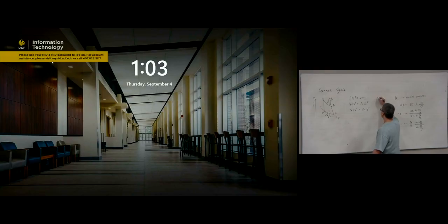We make some change, okay? We know that PV equals nRT as well, correct? Then these two equations we can transform this way. For the first one, we just use one PV and one VB. Then what we have is VB^(gamma minus 1) TB equals VC^(gamma minus 1) TC, right?